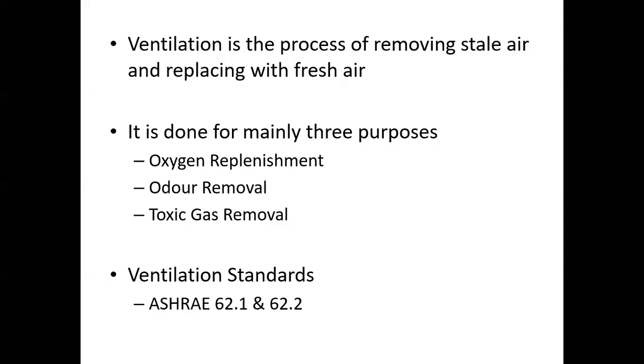Otherwise, if it's within an office area probably, there is no need of high wall AC, isn't it? We can simply go with those diffusers concept itself. If you need separate controlling, you can provide a VAV. So we can learn about VAV later in the class itself. So guys, that's all about the concept of this positive ventilation.